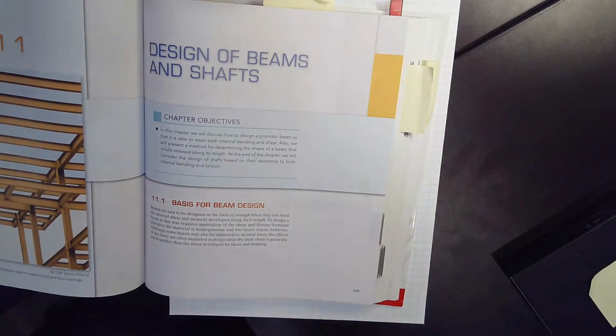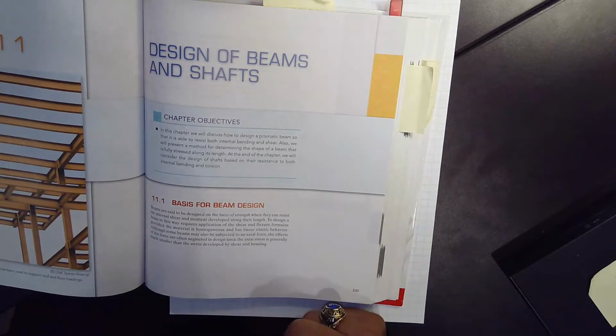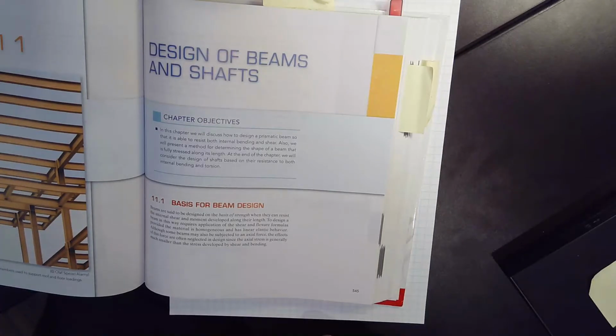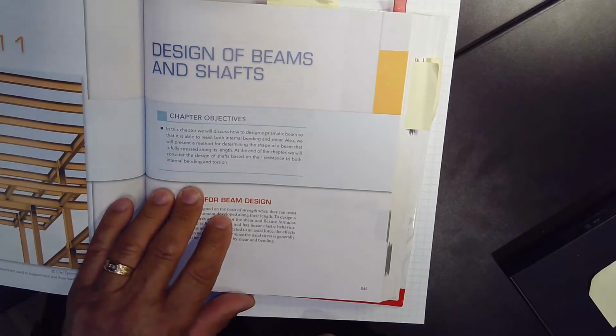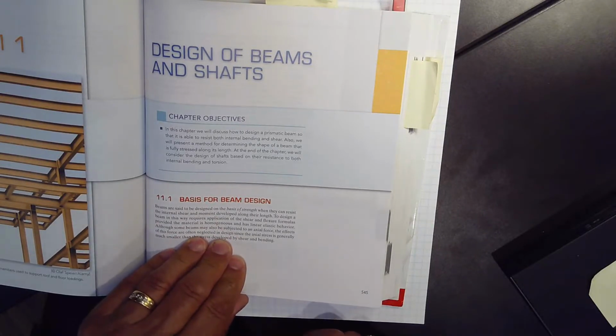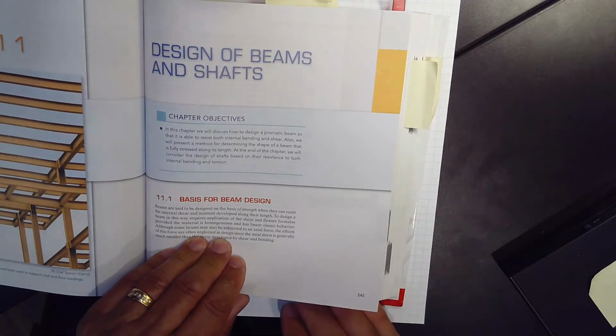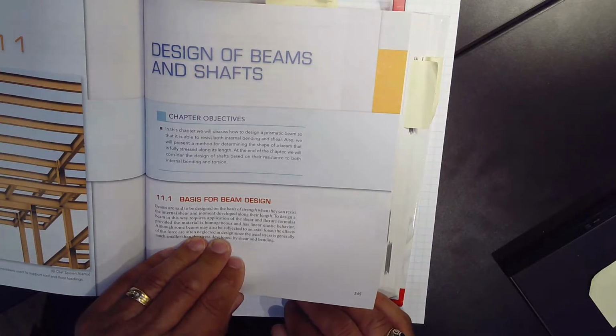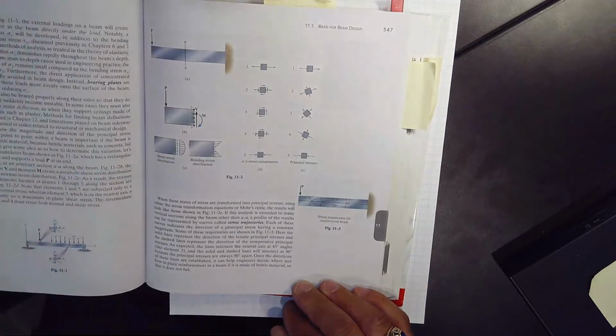Okay, the key thing here is that we are going to be looking at existing beam sizes and shaft sizes. And so we're going to be able to look up their section properties in a table somewhere. The shaft's a little different. We'll have to calculate a diameter, but then diameters only come from the store in certain sizes, and so we're going to round up to those sizes.